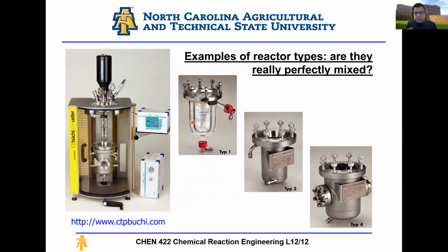such as mass transfer resistances and heat transfer resistances. As you can see on this one on the left here, we can introduce a sparger and see the effect, for example, of mixing speed on the reaction performance. Some of them, you see this one has a cooling jacket. You can have a look at the effect of coolant flow rate on the reaction performance, etc. And you have high pressure bombs here as well, where you can run the reaction at high pressure and do all types of things.